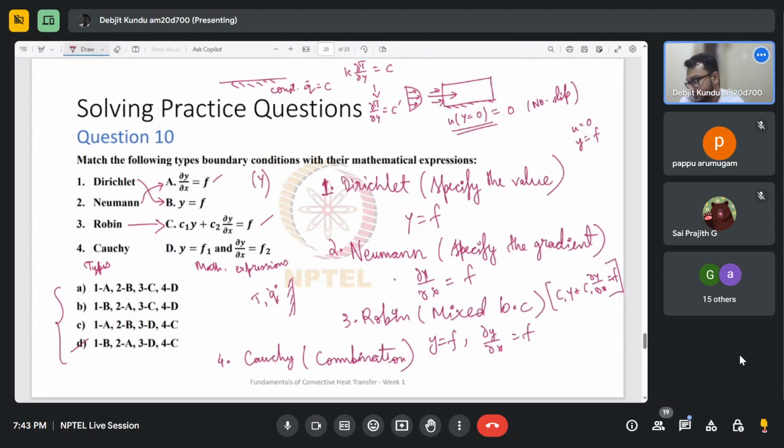So in case of convection, what happens is something like this. So this flux Q, let me write this. So the flux Q is a function of the temperature itself. So the heat flux is equal to the convective heat transfer coefficient H into T minus T infinity, which could be some temperature in the ambient.